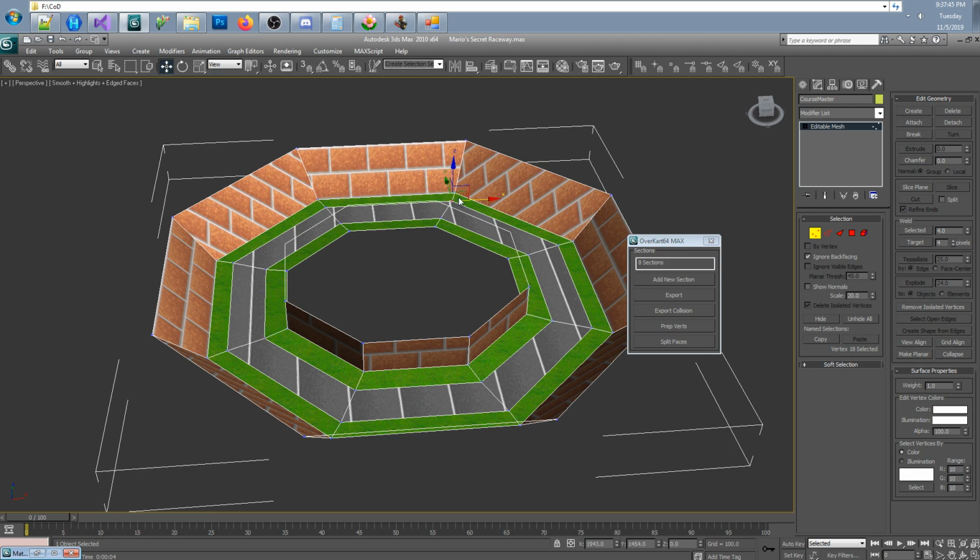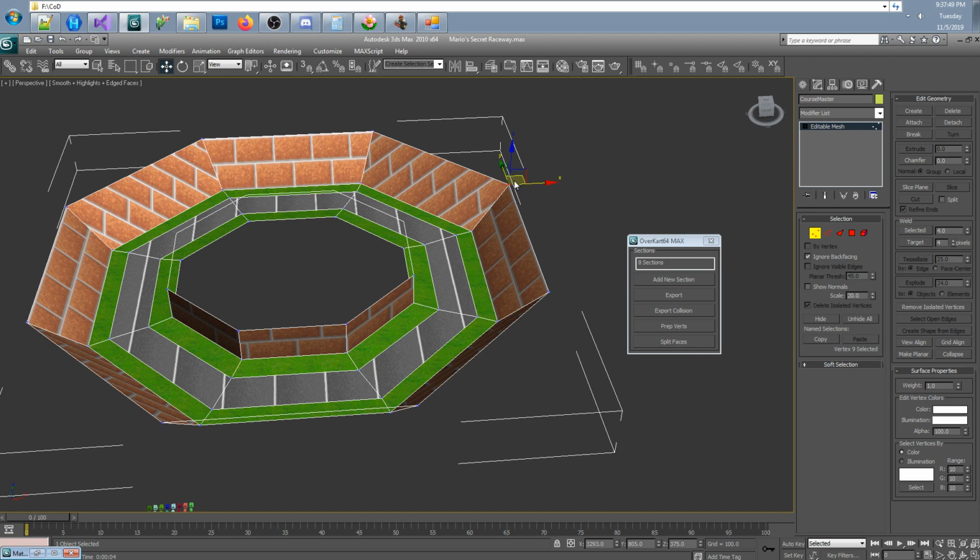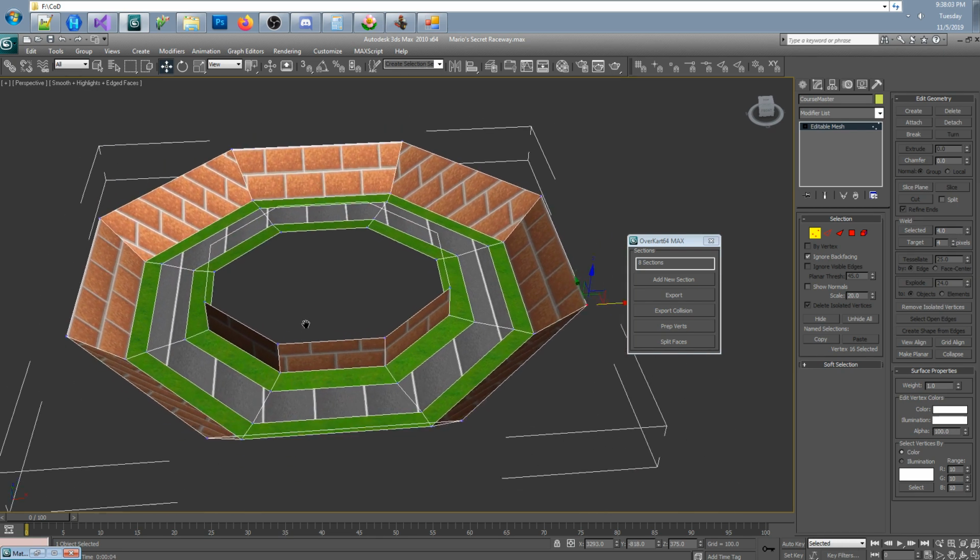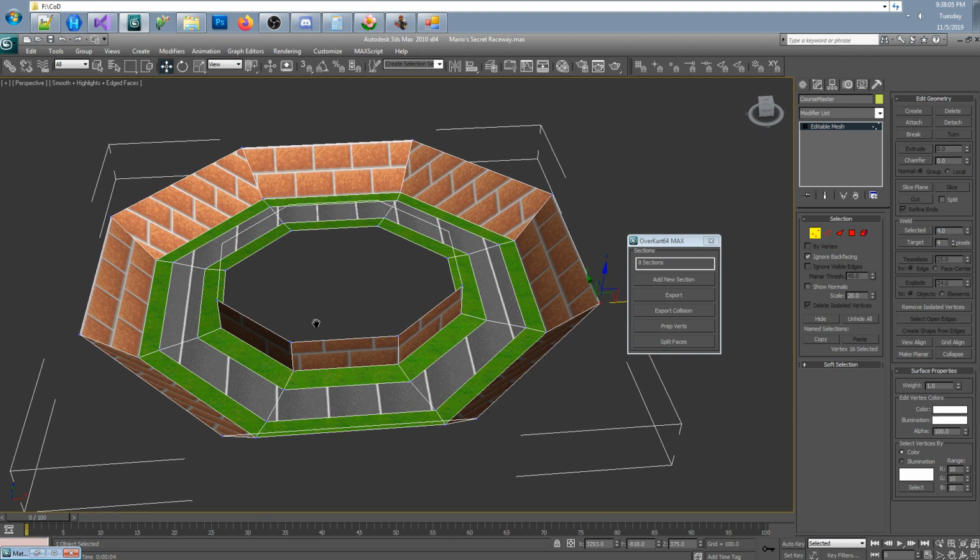This would have been done regardless if you export decimal values. However, you will not get to see what changes those roundings make to the geometry. And so it's better to prep them now so that you could see and make any adjustments you may need to in case there are any errors that come about from rounding the positions of the verts.